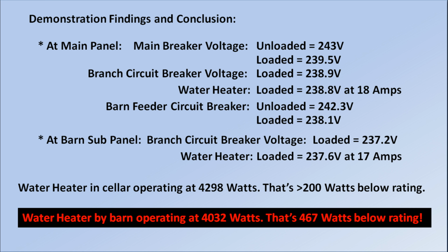Here's what we learned from this voltage drop demonstration. For one thing, I lost 6 volts from the unloaded main breaker to the barn sub panel, loaded at 17 amps. The amazing thing is, that's only 2.6% total voltage drop, so it's acceptable.